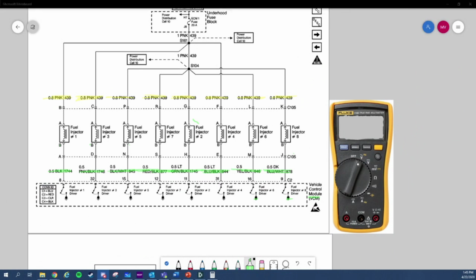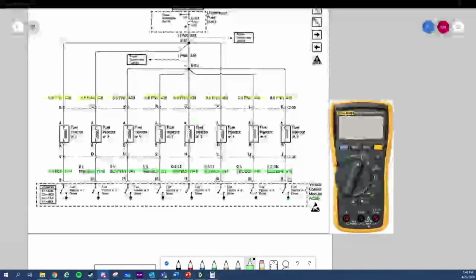What tells my injector when to pulsate? Probably an electronic signal from the vehicle control module. Yeah, there has to be some type of signal. And normally it's the signal coming from either a crankshaft position sensor or a camshaft position sensor, because this is going to tell my vehicle control module what position my piston is in. If it's coming down for a downward stroke, which means it's already sucking up air, then more than likely I'm going to want to shoot fuel into that because it's coming back up for a power stroke. Does that make sense? Yeah.